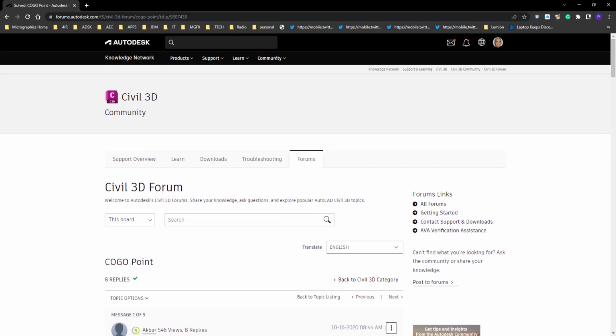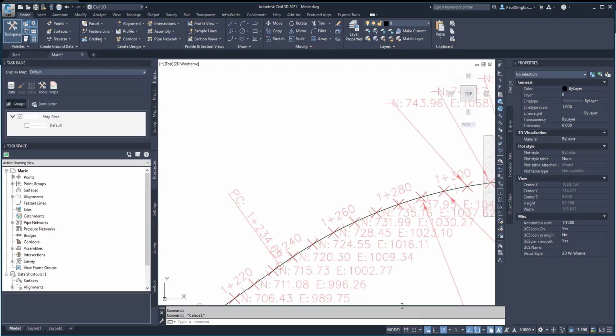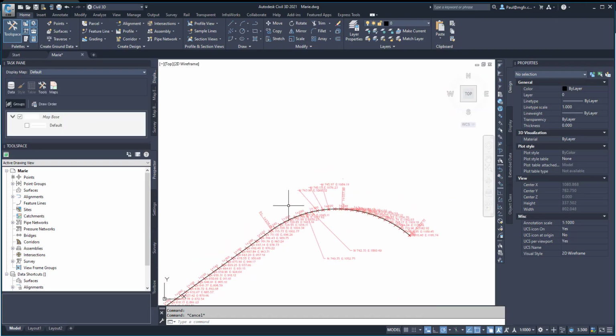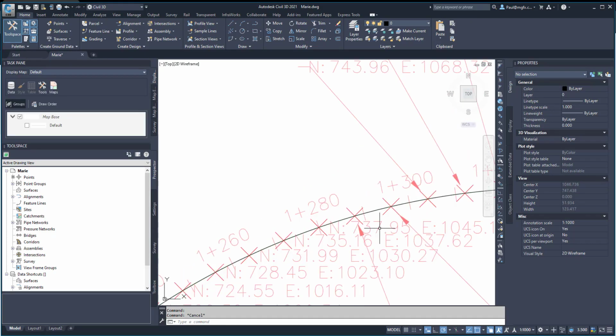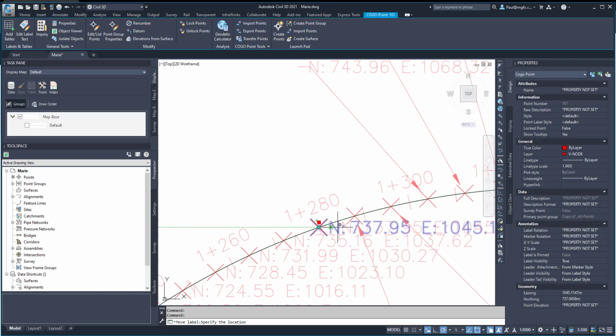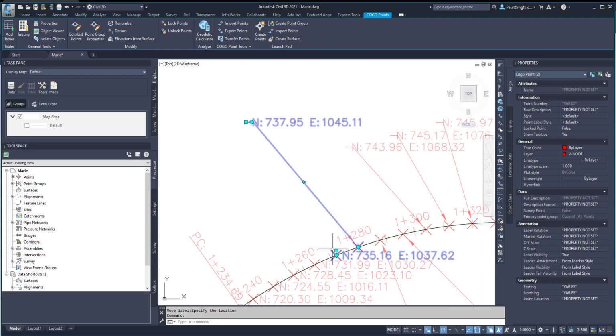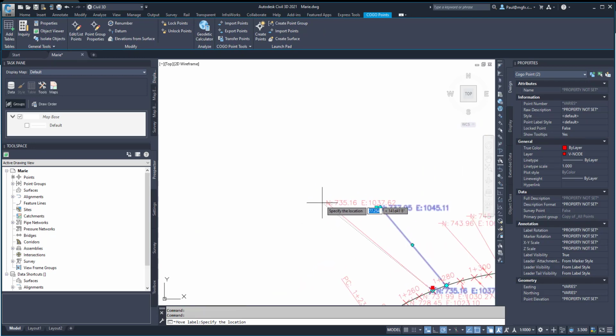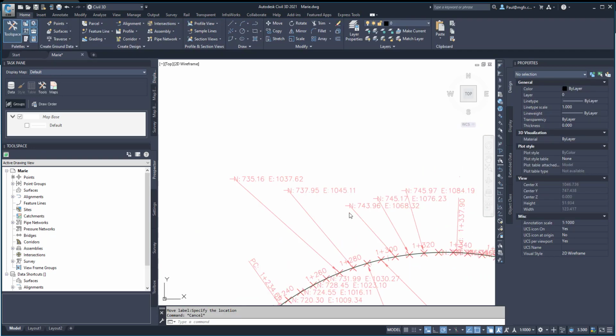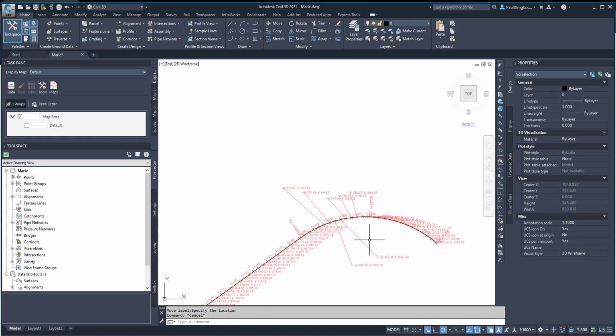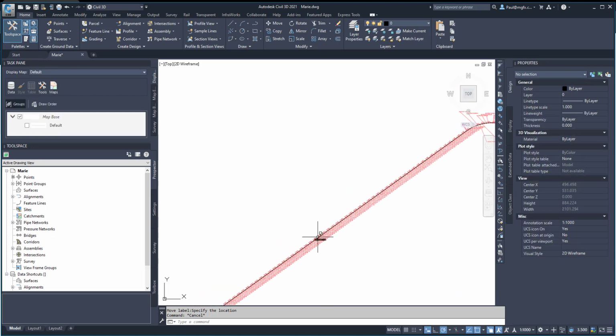We had a look at this script, or at the graph, and the client's brief was we must be able to drag the COGO point labels out into some other position. And now they would like that to be perpendicular. The orientation of the label at least must be perpendicular to the polyline. Obviously one can do the same with all of these ones over here.